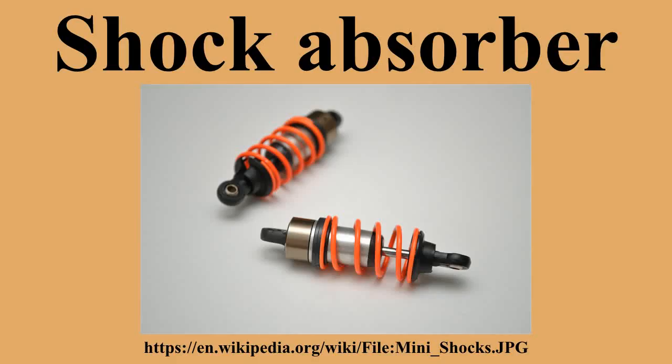These pistons are called the working piston and the dividing or floating piston, and they move in relative synchrony inside the pressure tube in response to changes in road smoothness. The two pistons also completely separate the shock's fluid and gas components.